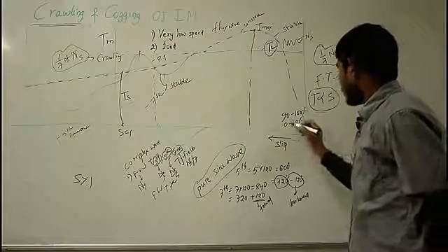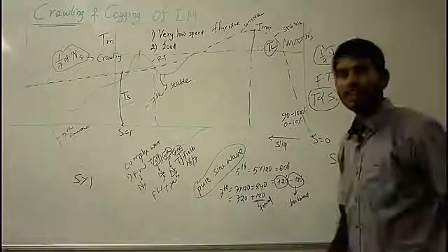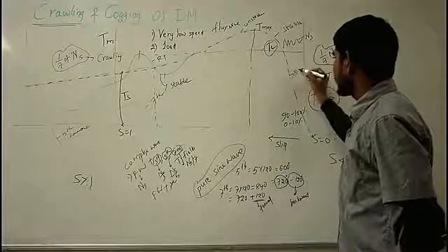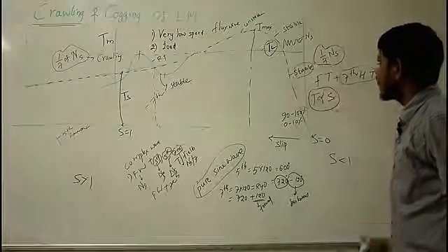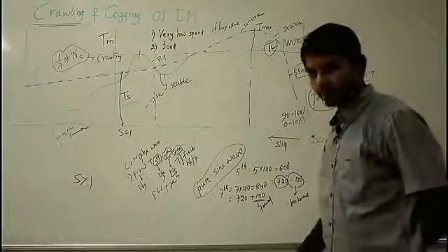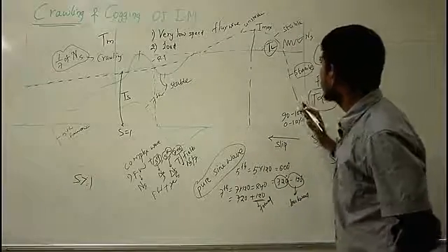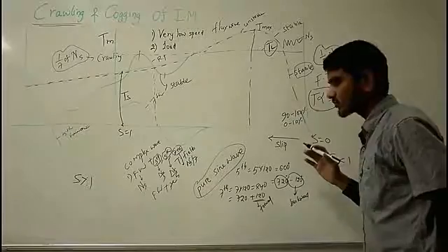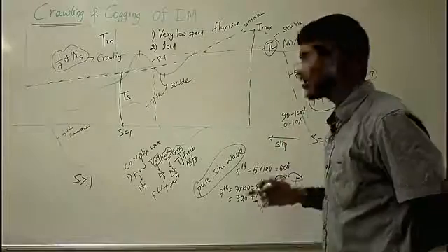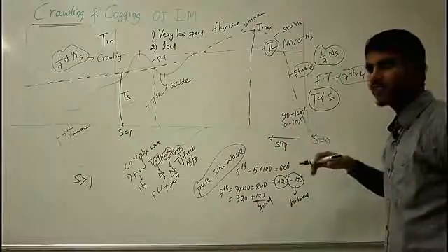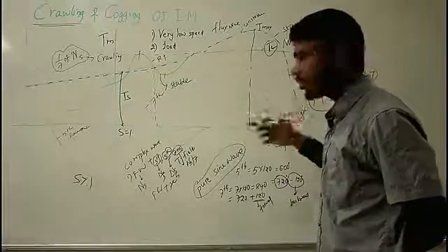Now, when the slip is low and the torque is proportional to your slip and it is operating at high speed, the motor settles at a stable position, and hence it is known as a stable region for your induction motor. And you can say this is the negative slope, and this adds friction to the motor, and this improves the damping, and this indirectly increases the stability of your motor. This is also known as internal electric damping of your motor.